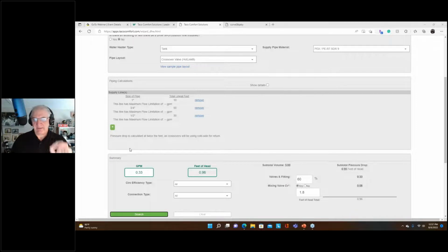That's terrific. The better place for that aquastat is at the last fixture, but that's the most inconvenient place for it. But it is the best place for it because we don't care what the water temperature is in the recirc line. So that's another way to turn the pump on and off. So it could be a plug-in and we just shut it off when the water temperature drops. Not a great way to go. Timer, shut the pump off with the aquastat when the water temperature gets to where we need it to be.